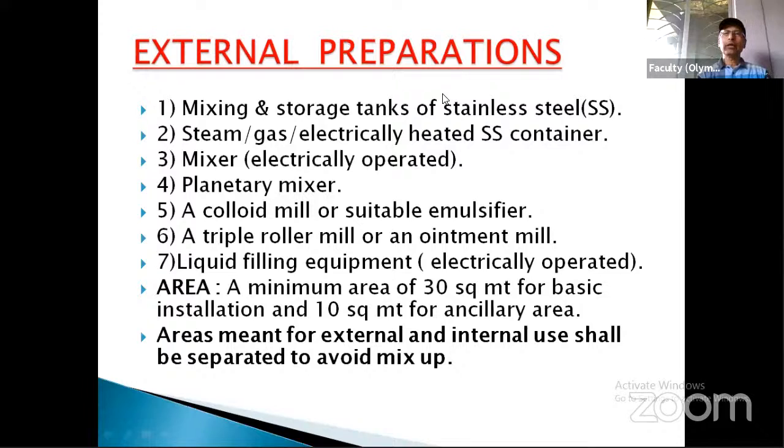And generally we consider it is not less than 200 square meter that is needed for providing these additional general facilities, like your cloakroom, the dress change room, your water treatment units, your quality control section, your restroom or canteens, your toilets, your quarantine area. All this area you have to provide.